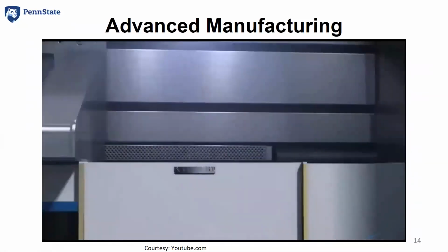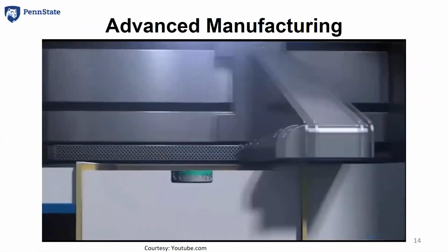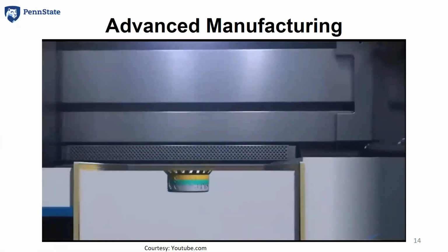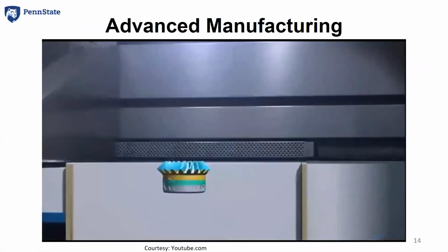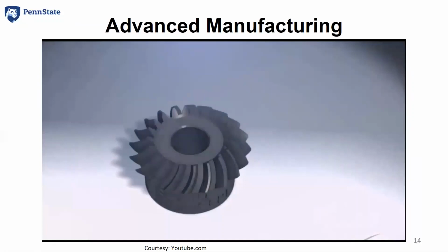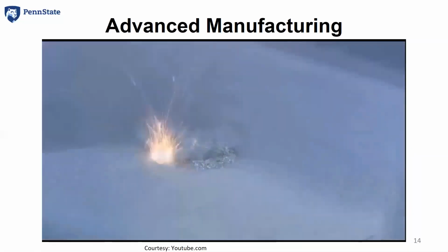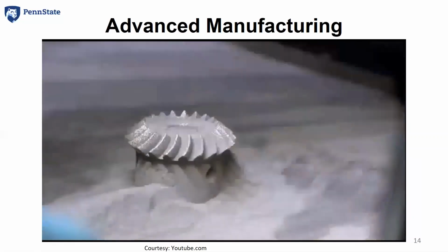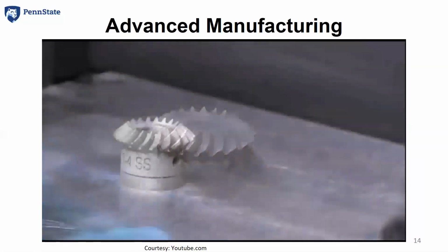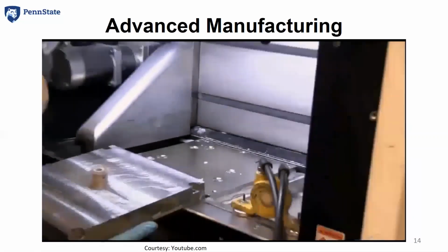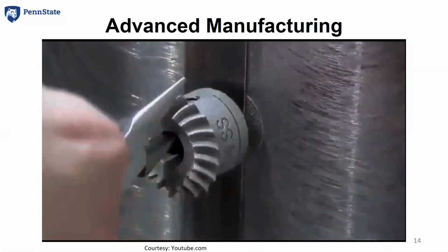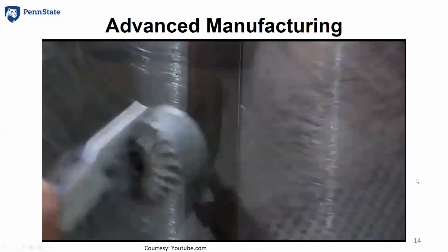Then we lower the powder bed and we spread another layer of the powder. And then we do the laser sintering again. So in the end, we will get a metal part. Okay? So this is 3D printing layer by layer. We spread the metal powder and we print it, and we spread it again. So in the end, we get a 3D printed metal part, and we can get it out of the chamber. This is additive manufacturing.